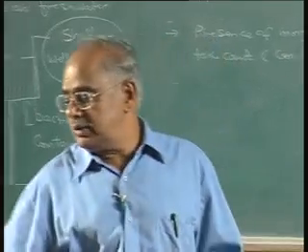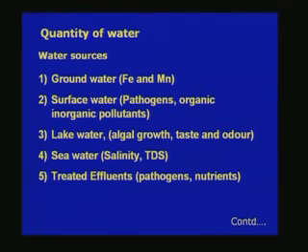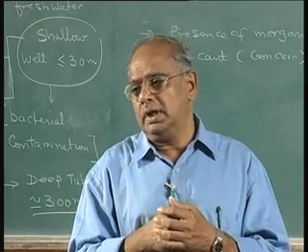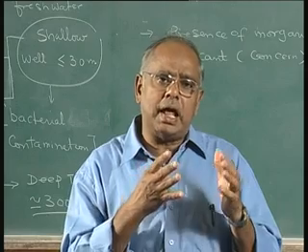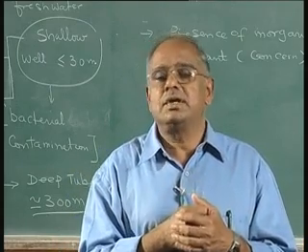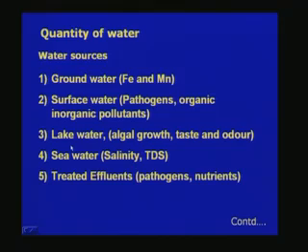Now let us go to the next thing, the lake waters. Lake waters are present in big reservoirs, and they have natural sedimentation in the reservoirs. Since there is no turbulence in the lake waters, algal growth will be more. The presence of algae itself produces taste and odor problems in water. So, if you are taking water from the lake, it would have some organics which cause taste and odor, and these problems have to be dealt with in our treatment.